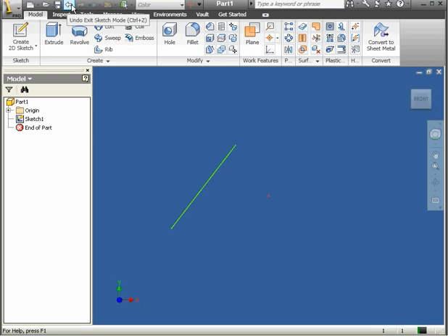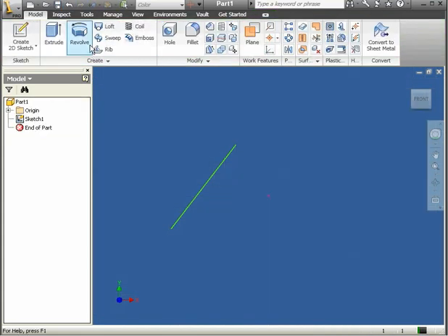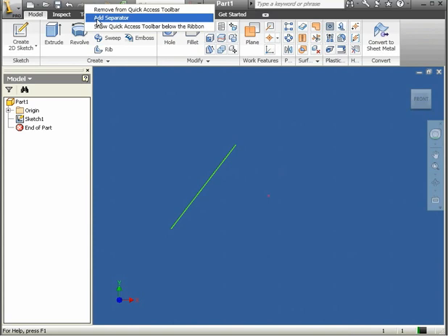Let's enter our sketch again. We'll double-click on the icon in the browser. Now let's go back to the Undo tool. When I mouse over it, the message has updated to undo our current last action, start sketching. Let's right-click on the Quick Access toolbar now. I want to check out some of the contextual menu options. From here, we can easily remove a command from the toolbar, add a separator, or show the Quick Access toolbar underneath the ribbon instead of on top. Here's my separator pipe. To remove that separator, right-click again and select Remove from the Quick Access toolbar.